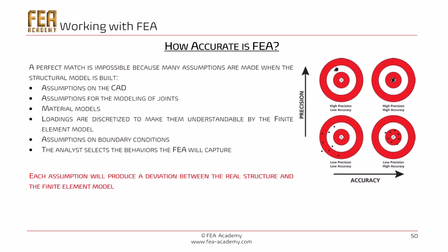So to conclude on accuracy, keep in mind that to produce a highly accurate FEA, the analyst has to pay close attention to many points and perfect them, especially if the model is composed of several assembled parts. A single component model will easily match the real life, while complex assembly will require more effort.